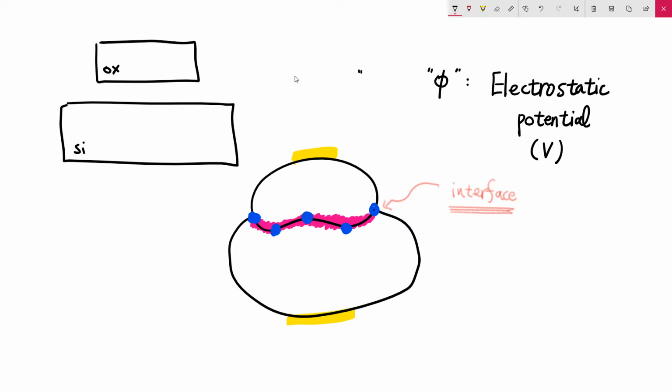Maybe you understand: electron density and hole density are those quantities we have to consider. So now think about a general case where you have to solve the Poisson equation, the electron continuity equation, and the hole continuity equation for these three quantities. Then what did you do?